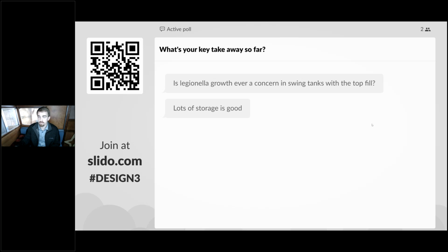And then we have a follow-up comment to that from Jack. If you're using city water with chlorine treatment, you are unlikely to have Legionella concerns. Right. Yeah, so that is an advantage there with the chlorine treatment. Sometimes engineers, based off previous experience, want to avoid mixing valves and actually use UV, I don't know if you call it filtration, but UV water treatment to get rid of that Legionella risk as well. So there are alternates to bringing it up to that higher storage temperature, but additional considerations with each of those alternates for sure.